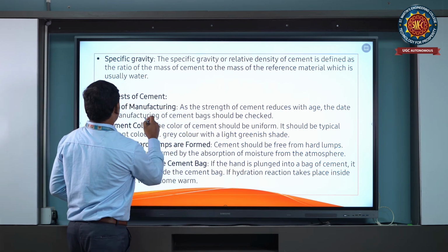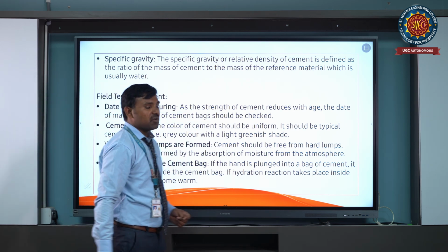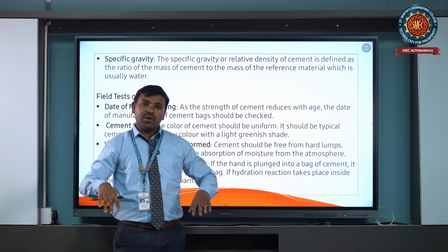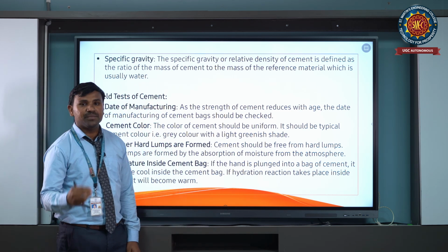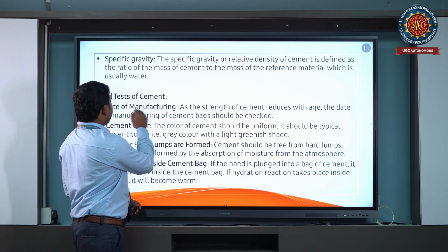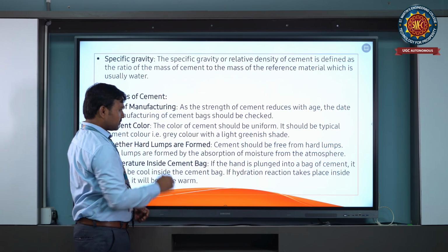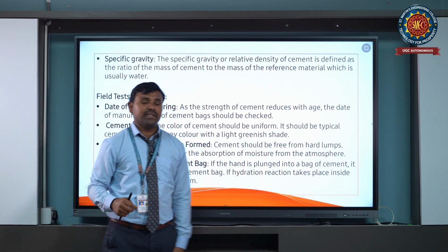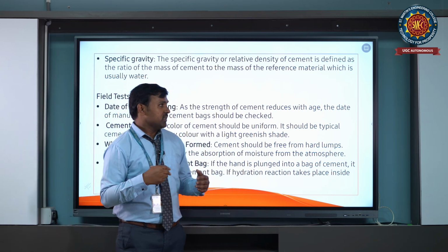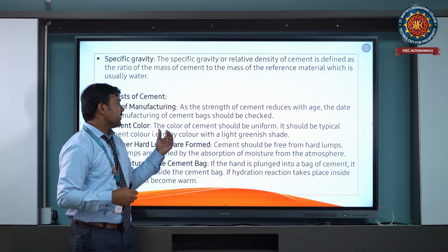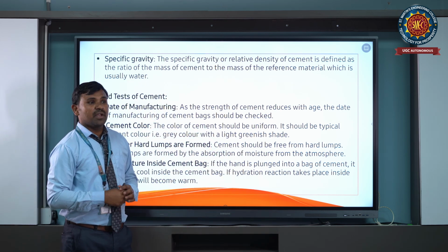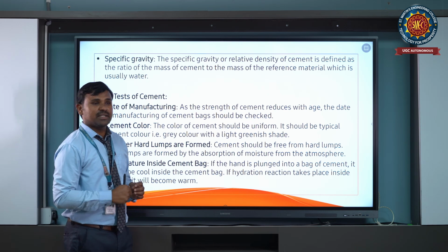And next about field tests of cement. These are the main tests which we can do anywhere in the field by observing, starting with the date of manufacturing. The strength of the cement reduces with age. The date of manufacturing of the cement bag should always be checked before bringing it to the construction site.